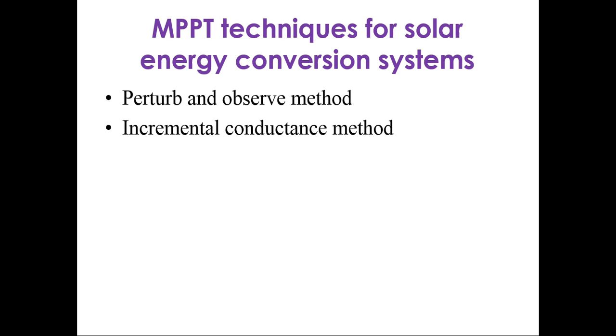So this is the advantage. Let's take a practical example. If we have a 17 volt PV voltage and my battery voltage is 12, and if I buck the voltage from 17 to 12, at that time the current in the output is marginally increased. So I'll get more output current if we have the buck converter.